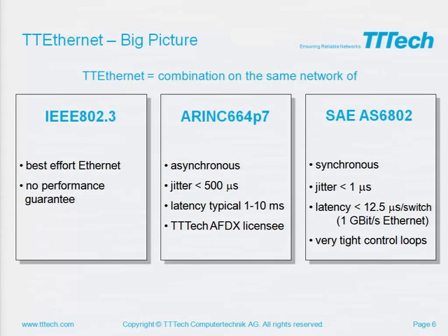And in addition to that, we have added a quality of service which is fully synchronous. So we have a fully synchronous behavior, and therefore we need some kind of synchronization in the network. On top of this synchronization, we then transmit messages according to a predefined schedule. Here we get down to very, very low jitters and well-defined latencies depending on the setup itself. And this is then a quality of service for standard Ethernet that enhances standard Ethernet to be usable for highly reliable systems.